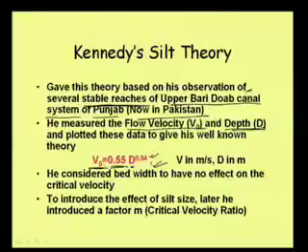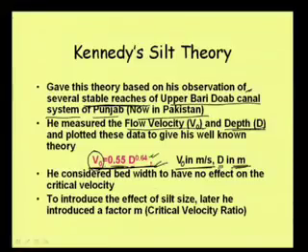So, that equation is this one, V0 is equal to 0.5 d to the power 0.64, where V0 is in meter per second and d is in meter. Okay. So, this was the popular and famous formula of Kennedy, and as I said, he did not consider the effect of the width of the channel on critical velocity.